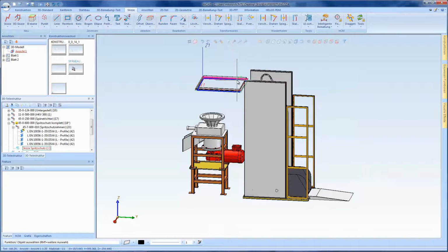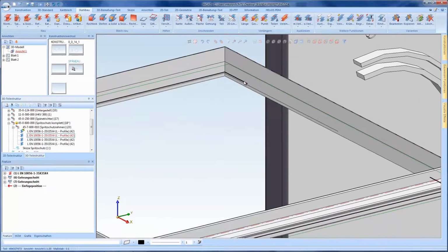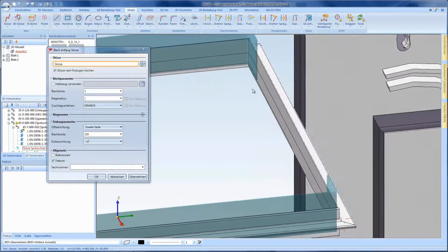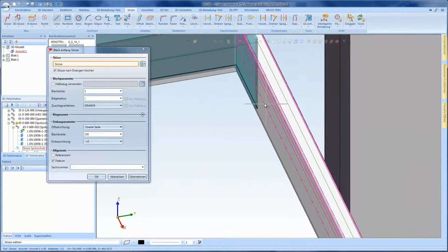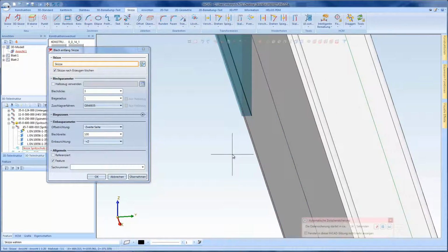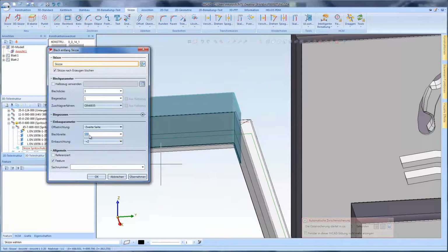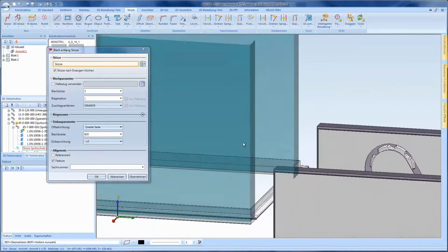The first improvement is the sheet along sketch function. Now there is a direct preview of how the sheet is created. This means you can already see from the sketch line how thick the material will be. You can also still modify the direction, and the sheet thickness is in +Z, in this case 100 mm. If you want this to be higher, you can of course change that, and we see the result right away.